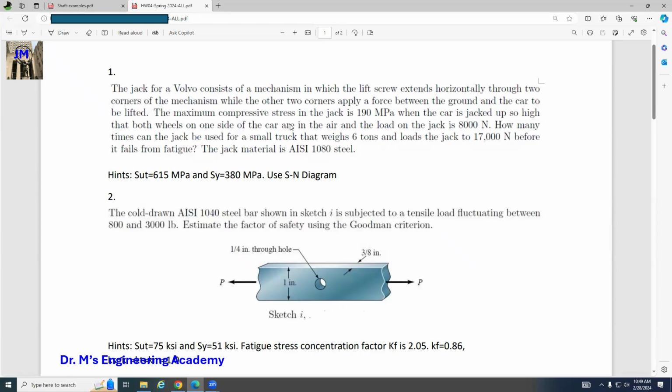So we know that rho equals 7860 kilogram per cubic meter. Then IM equals, and you just plug in everything: pi over 32, 7860, then 0.0254, and d to the power 4. What is this, guys?